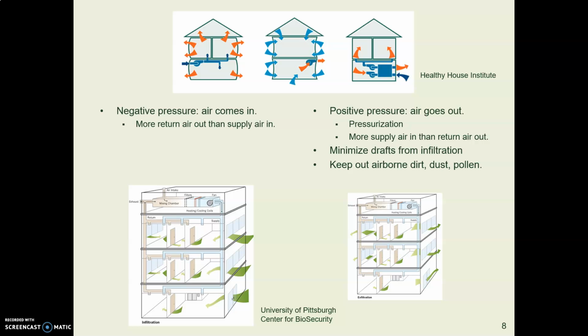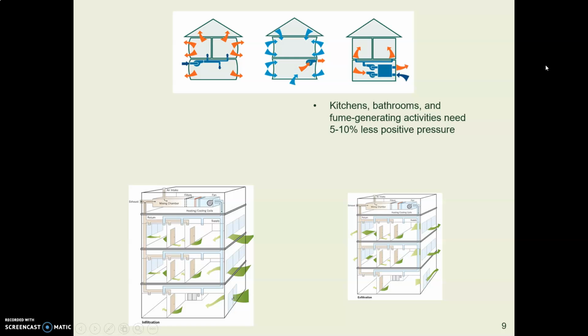Like if your commercial building is next to a chemical manufacturing plant, you do not want fumes infiltrating, so you would pressurize your rooms. If, for some reason, you want air to slip in, then you would have your pressure be just slightly lower.